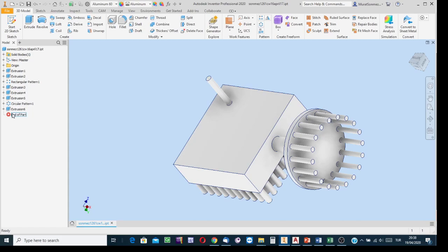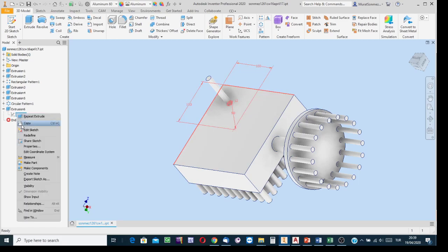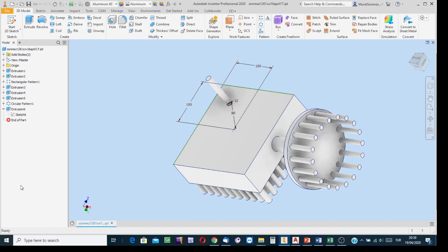First click on the associated cross, drop this list, and in the list you can find the sketch icon. It corresponds not to the sketch of the others, but the sketch of that one. And in this sketch I have the necessary point. Right click and then make the sketch visible, selecting the visibility option.